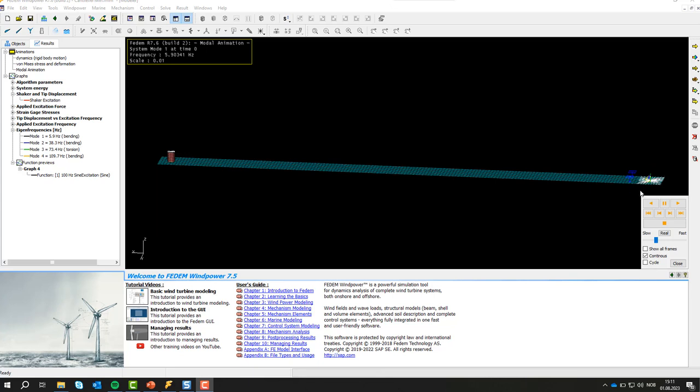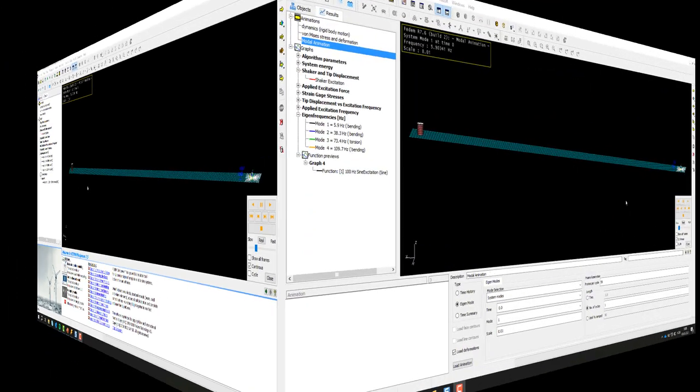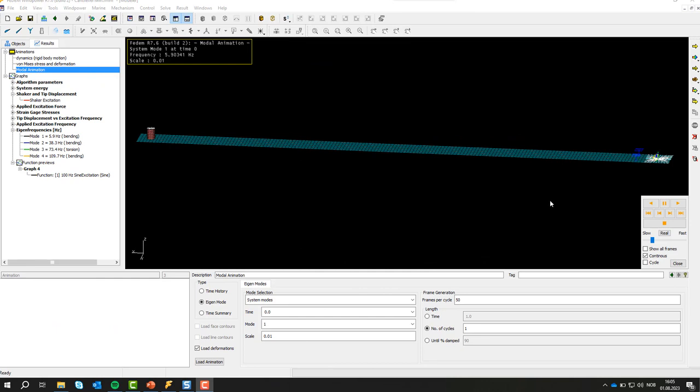I could also add stiffness in all directions here, but I still have no numbers for those stiffnesses. So this clamping is assumed to be infinite stiff, as in my analytical calculations. However, I've now added the lump mass here, so I presume that my modal analysis will be more accurate than the analytical calculations. Let's have a look at the results.